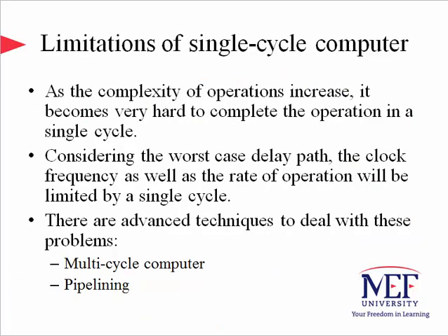Finally, I want to mention the limitations of the single cycle computer. First of all, you might guess that as the complexity of the operations required by the instructions grows, it will become very hard to complete the operation in a single cycle. And we want our computers to run fast, but this requirement will be transformed into a higher clock rate. Considering the worst case delay path, the rate of the clock will be limited by a single cycle time, which will be governed by the worst case delay due to running a particular operation.